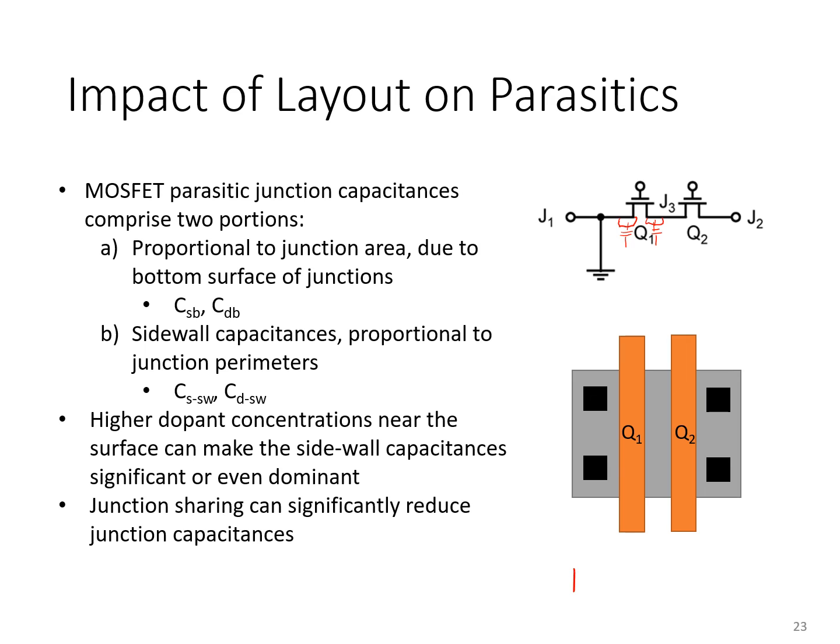So that's what's being depicted here, the bottom right corner of the slide. It's effectively a top view of the transistors, which is the way in which an integrated circuit is ultimately designed in CAD tools. You effectively draw the top view of each layer of the integrated circuit.